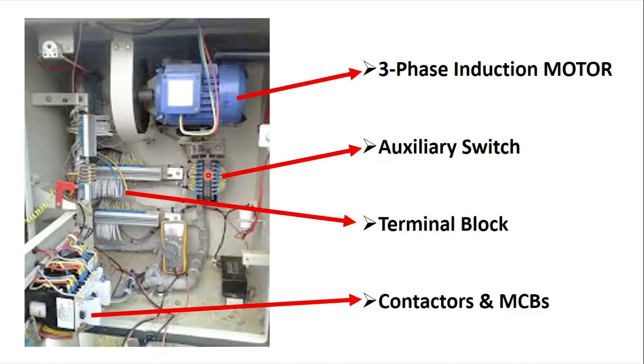So the fault might be there in this also, because it happened once with me when I was finding an earth fault. At that time I was not able to find out where the fault was, but when we disconnected the two wires of a contact, then that DC system became healthy. Then we found that yeah, there was a problem in this itself. So this may occur anywhere. That's why I have taken an example of this isolator.